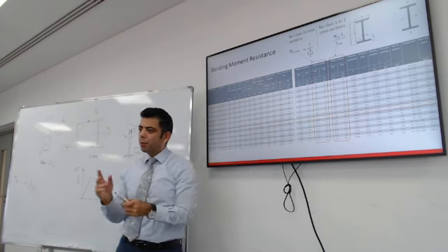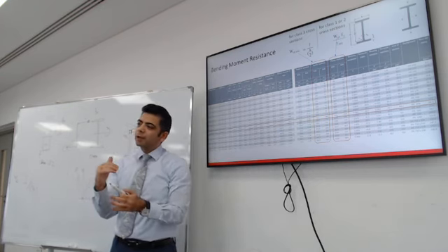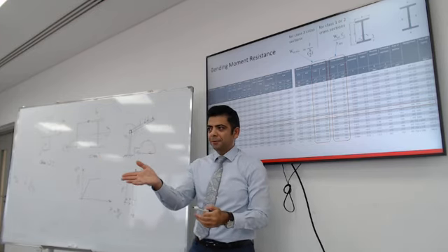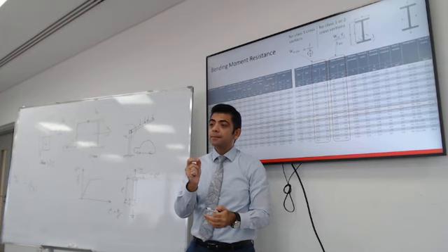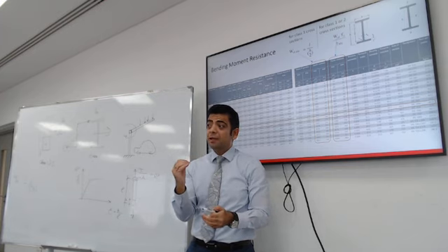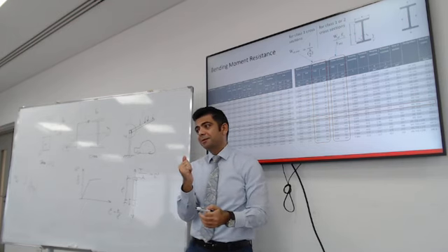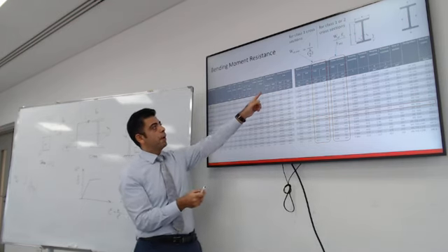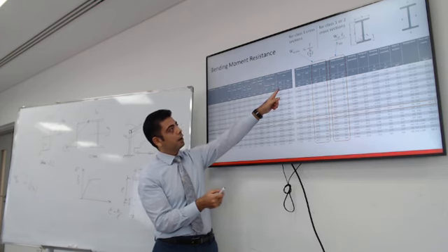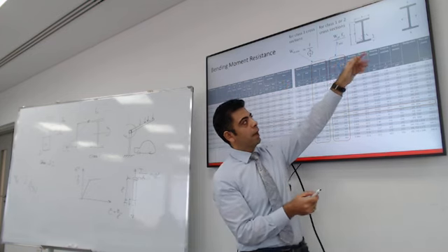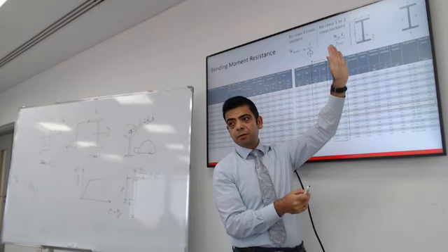So what does that mean? What is the moment of inertia with respect to the y-axis? The second moment of area, the inertia in the y direction and the inertia in the z direction. This is very important. The moment of inertia about an axis is the resistance to rotation about that axis. So where is y and where is z? Y is the horizontal, z is the vertical.